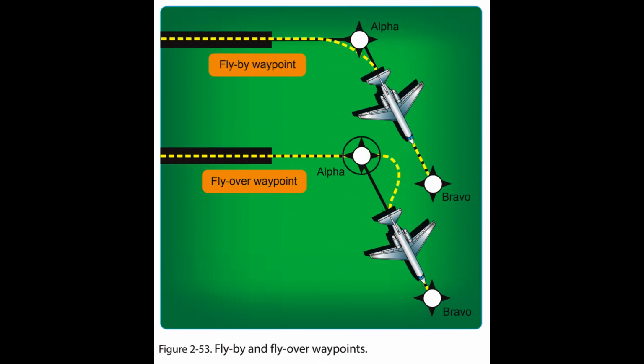Waypoints. Waypoints are predetermined geographical locations that are defined in terms of latitude/longitude coordinates or fixes, used to define an RNAV route or the flight path of an aircraft employing RNAV. Waypoints may be a simple named point in space or may be associated with existing navaids, intersections, or fixes. A waypoint is most often used to indicate a change in direction, speed, or altitude along the desired path.